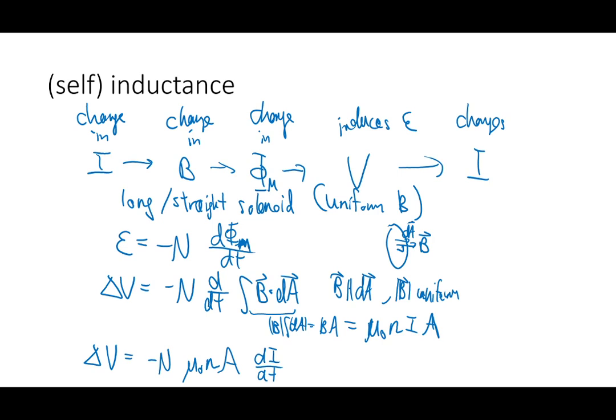And so now we have a relation for things that refer to circuits, voltage on one side, current on the other. And we have a bunch of more or less constants in time based on the geometry of my coil. So similar to how we encapsulate all these geometric properties of, say, a capacitor and call that capacitance, we can likewise make up a name for this thing and call this inductance, with the symbol L. And the unit for inductance is measured in henries, H.